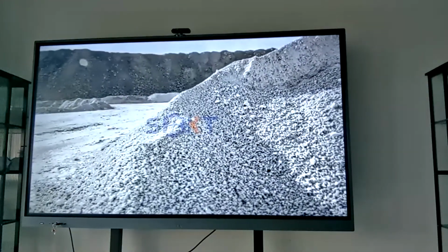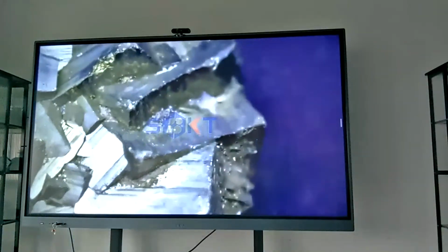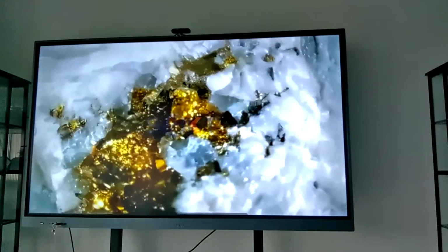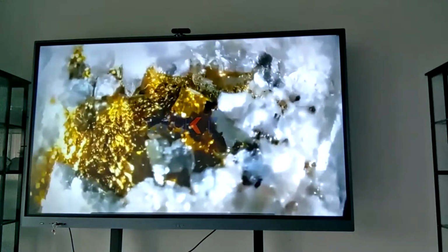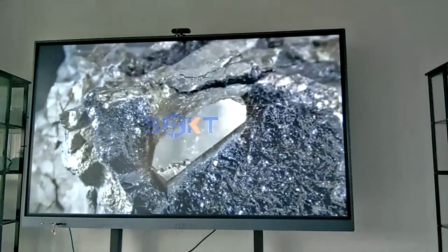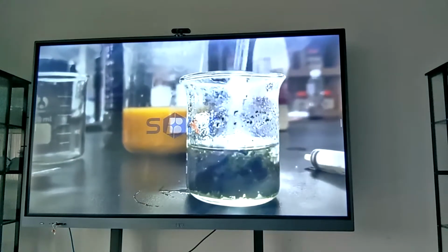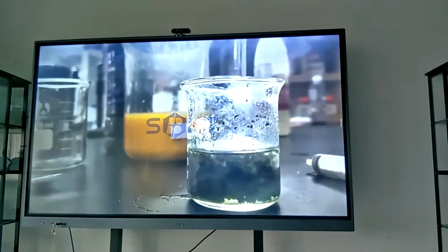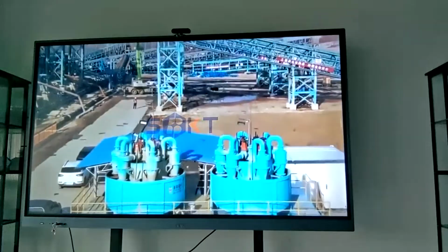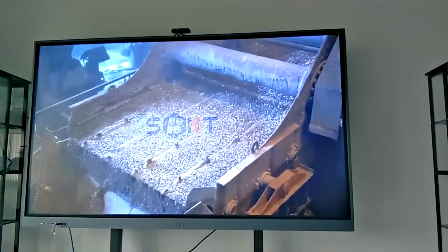Gravity separation recovers coarse gold particles early, preventing loss or overgrinding during the grind cycle. Filtration recovers remaining fine gold particles and gold from sulfides. If it contains coarse gold particle size, use gravity separation, and then filtration. Fine particles disseminated without coarse gold particles: flotation to obtain gold concentrate.